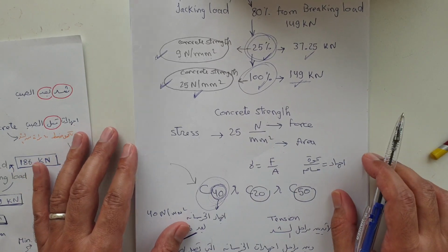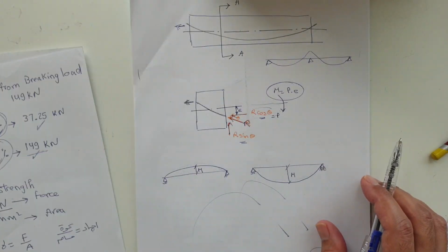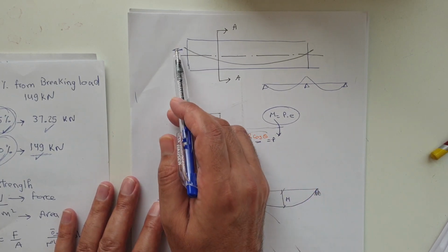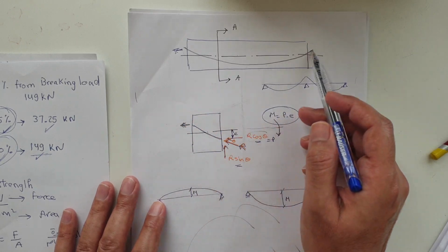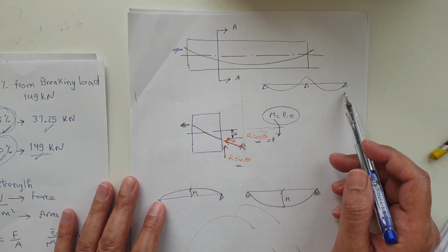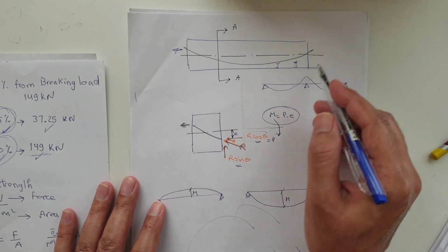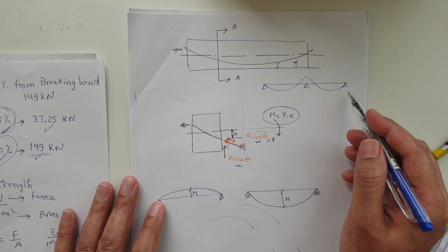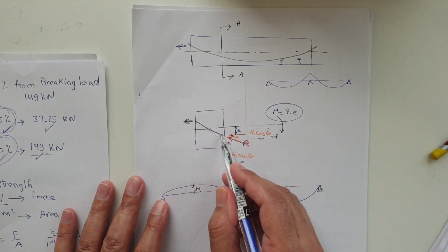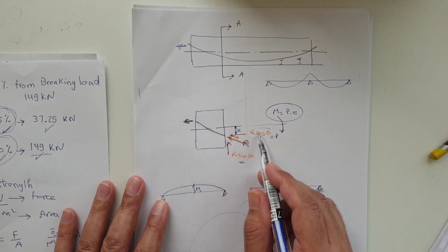So there is a relation between the stress applied on the strand and the strength of the concrete or cube test. But how can we understand the idea of stressing the strand? We put the strand above the chairs and it forms a curve, the same as the curve of the moment in the slab. So we fix the chair under the strand to make this curve as per the moment effect on the slab. If we take one section here, this is the strand and this is the force. Actually, we take the force in two directions, x and y.